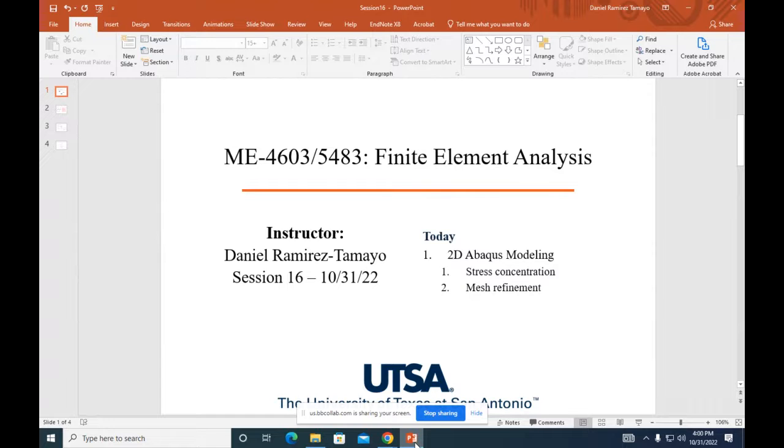So it's a really cool class to see the basis of fracture mechanics, and then we are gonna see the effects of mesh refinement, right? Because if you have a really coarse mesh, it's super simple to mesh and it solves something, and then you see some colors, but the fact that Abaqus is giving you a solution doesn't necessarily mean that the answer is correct, all right? Today we are gonna check how to perform a really good mesh refinement strategy for this simple problem, but you can extrapolate what we cover here to your particular projects.